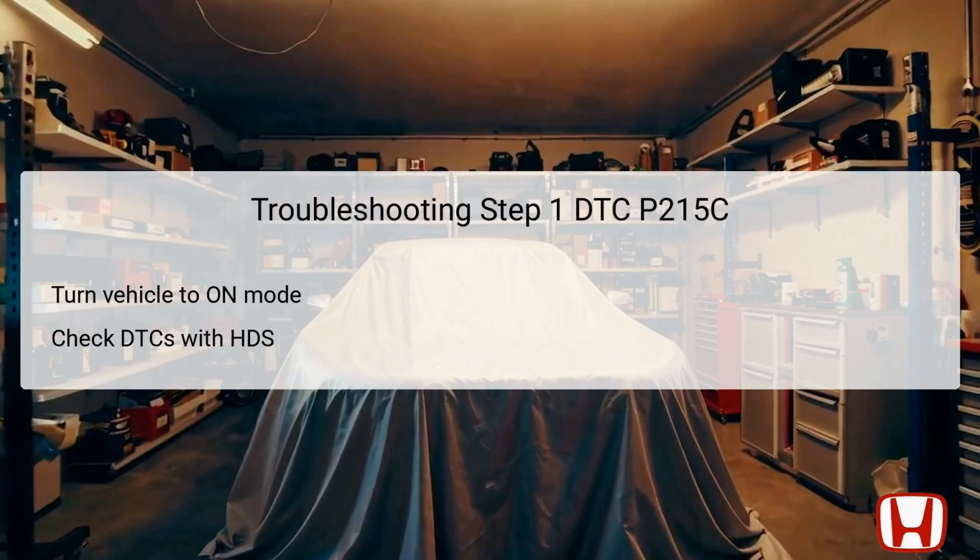By identifying whether there are additional codes such as P0500, no vehicle speed sensor signal, or P0720, output shaft speed sensor malfunction, technicians can narrow down their diagnostic focus. If other codes are present, one should follow the respective troubleshooting steps for those codes before proceeding.